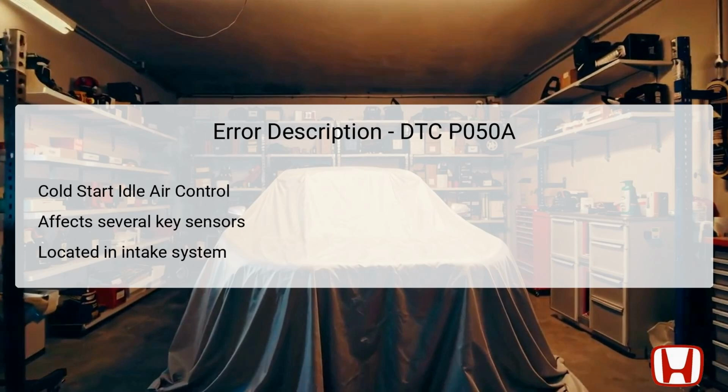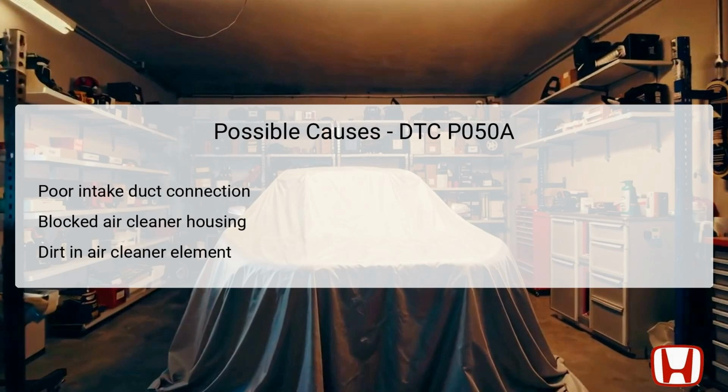The electronic throttle control actuator is responsible for regulating airflow based on instructions from the PCM. The PCM evaluates inputs from the MAF sensor and IAT sensor to maintain proper engine operation. If there are blockages or faulty sensors, the engine's idle can be adversely affected, leading to performance issues. These components are typically located within the intake system of the vehicle, making visual checks an essential part of the troubleshooting process. Several underlying issues can cause DTC P050A.